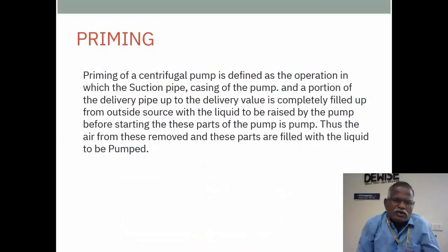Priming. Priming is very important. Priming of a centrifugal pump is defined as follows: the suction pipe, the casing of the pump, and a portion of the delivery pipe up to the delivery valve are completely filled with water, and air is removed from these parts.